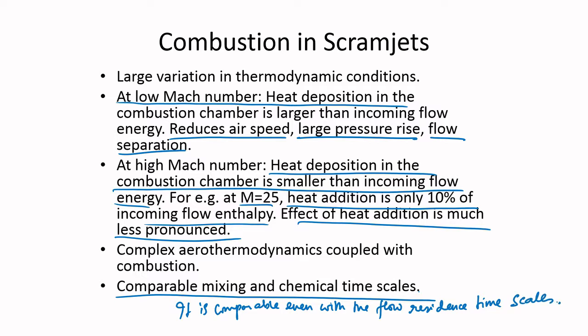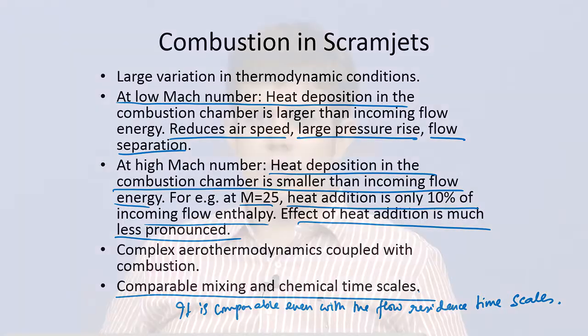So the flow residence time scales, the mixing time scales and the chemical time scales are all similar. That means there is very strong turbulence chemistry interaction, and that poses a great challenge to flame stabilization. So these are the different challenges that one encounters in a scramjet combustor.